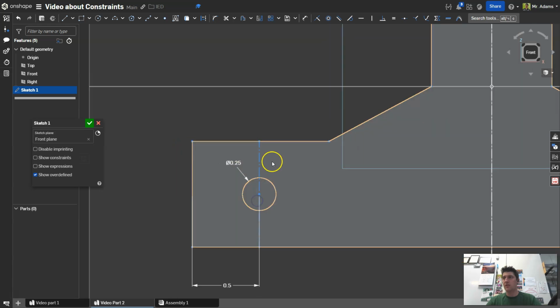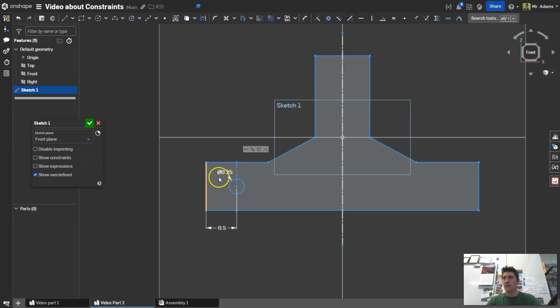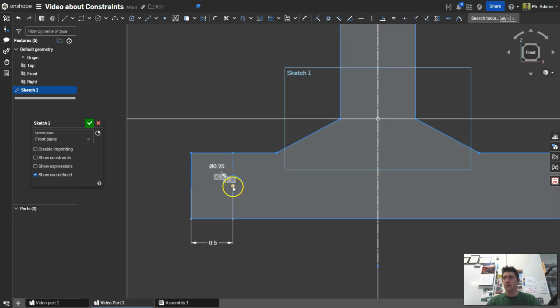Even if I change the size of this shape, because it doesn't have a dimension yet, the circle is always in the dead center. I could also use a midpoint constraint to create a constraint where this circle is locked in the middle as well. But I wanted to use an opportunity to show you the equal constraint. It's a very useful tool.